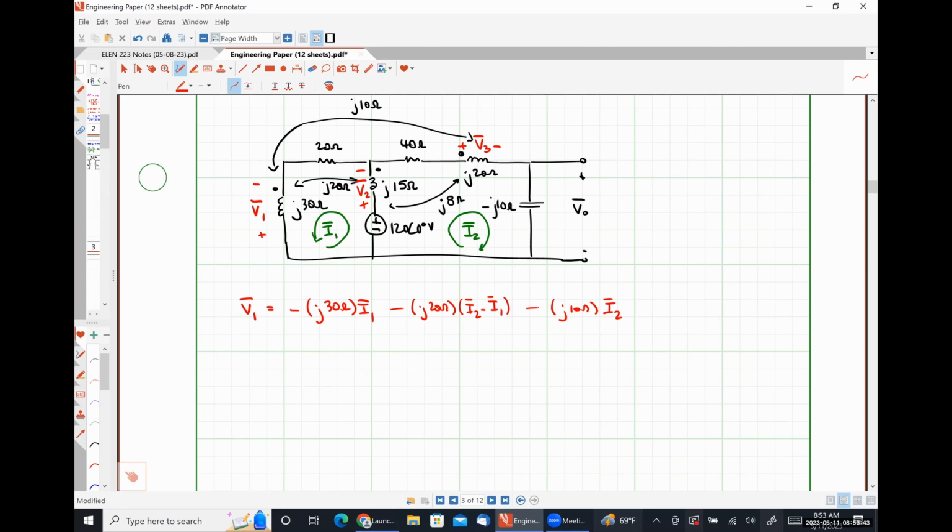So to make your life the easiest when solving a problem like this, it's usually the best idea to put the positive polarity terminal with the dot in every case. And then whatever current flows into the positive polarity terminal will give you positive signs for everything. But something like this is exactly what's going to be on your test, where I'm making you do it to where it's not all just going to come out to be positive signs.